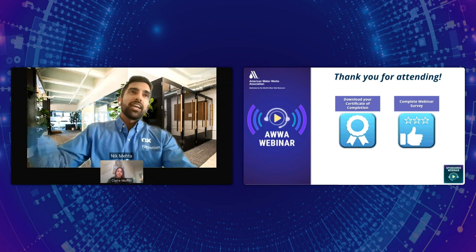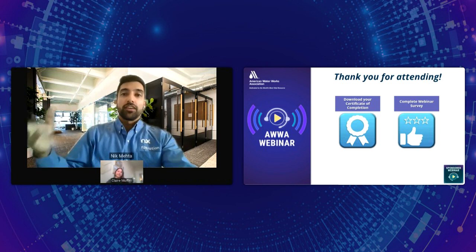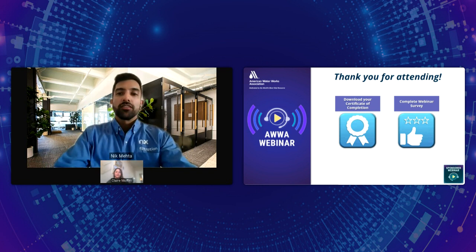So we concentrate the PFAS and we separate it from the main process stream. So you can use your permeate for whatever you need to. And then from there, this concentrate can be used for, say, a foam fractionation technology to do an extreme concentration step of specifically the PFAS, which then makes it appropriate for further destruction technology, whether that's electrochemical oxidation or high temperature alkaline treatment or supercritical water oxidation.